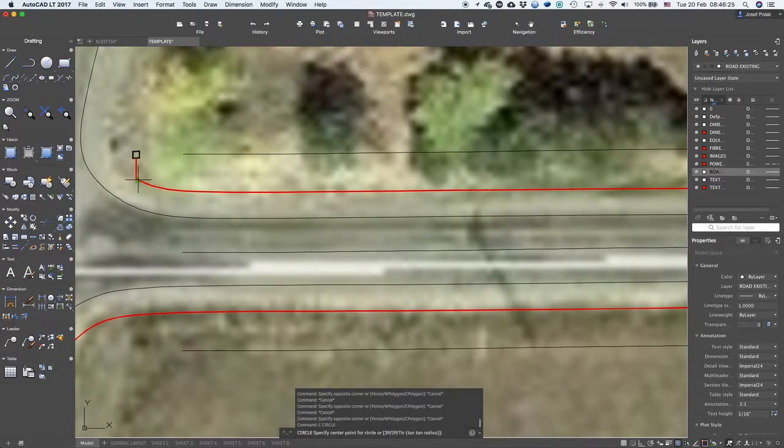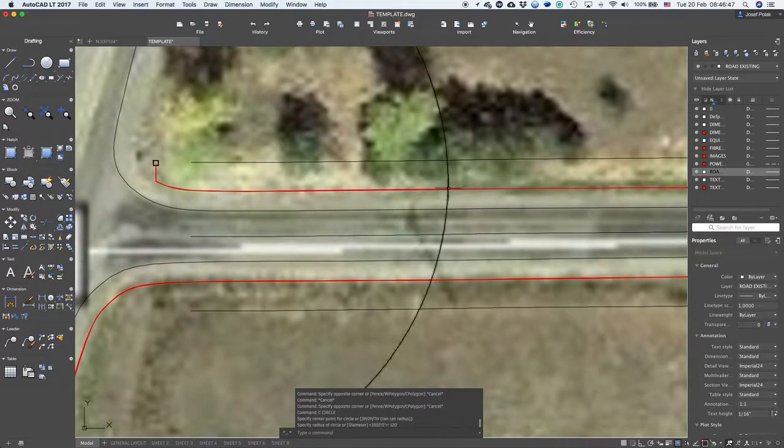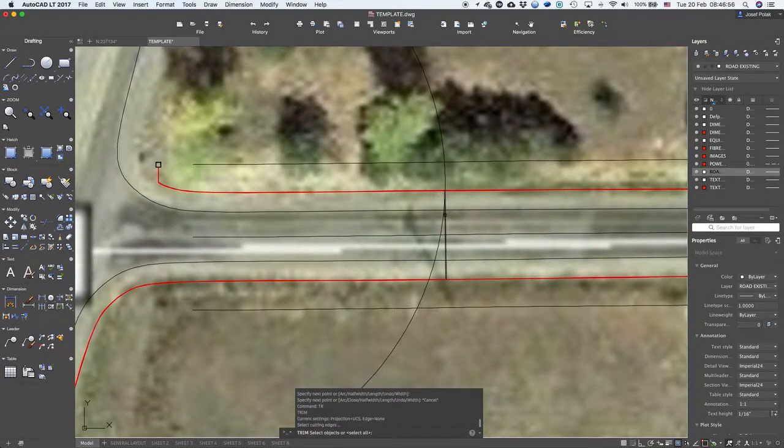I just draw a circle with the center at my starting point, and the distance, as we said, is 120 feet. So if I set the radius as 120 feet, it will show me where the start of the bore is. So I draw a polyline there to the other side of the road, and I can trim to here and here. I delete the circle and match the properties.